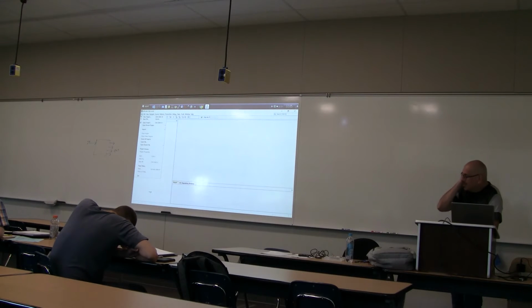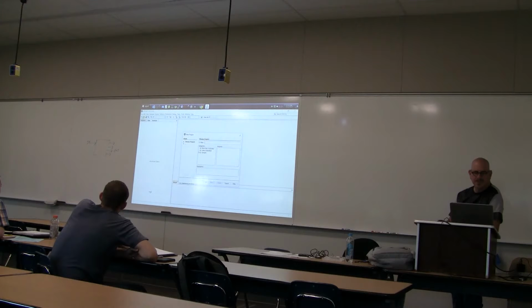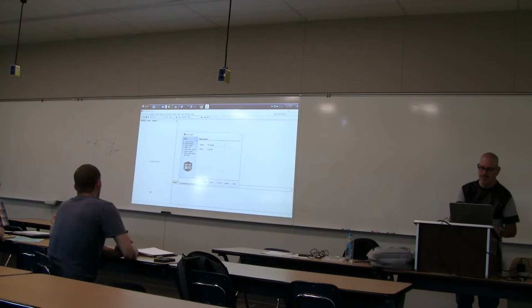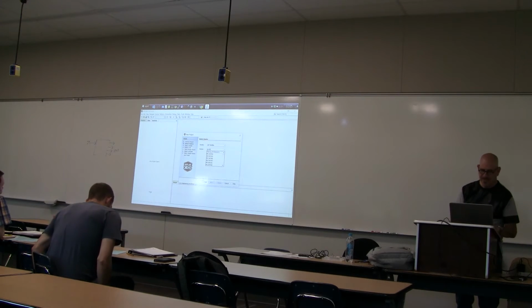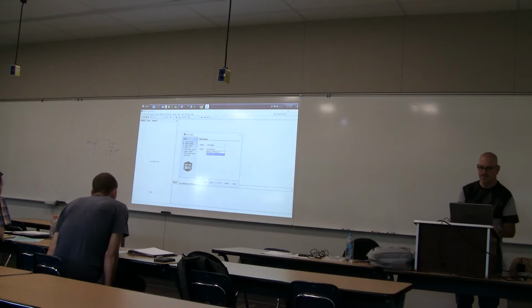So I don't want to run through the whole lab for you here because that's half the fun of it, is doing it yourselves. But let me just show you an example of getting this thing started. So I'm going to say File, New Project. And I'm going to do a standalone project. And then down here under device, we've got to specify PIC 18F1220.